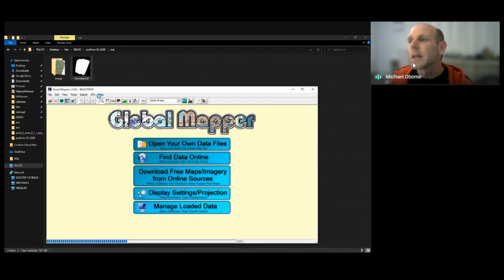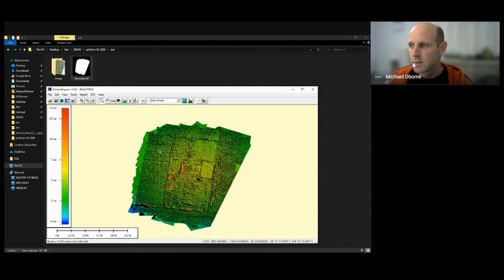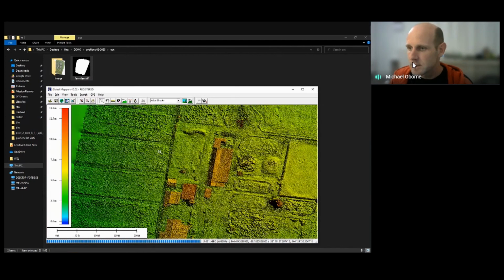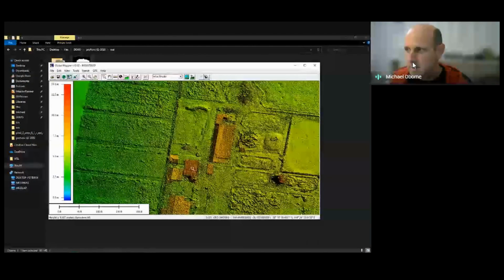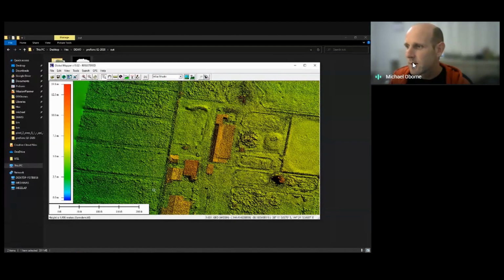The reason I'm telling you about the visual and the DEM is that this is the DEM of that photo data. You can see there's high points. If you look down in the bottom left-hand corner here, you can see the height. That's 9.17 meters, and over here we're at 7 meters. Ground level there is about 5 meters. So you can see the area here of the DEM.